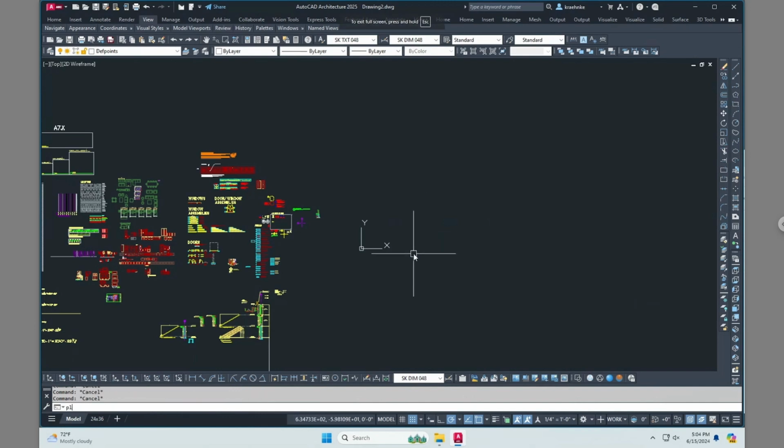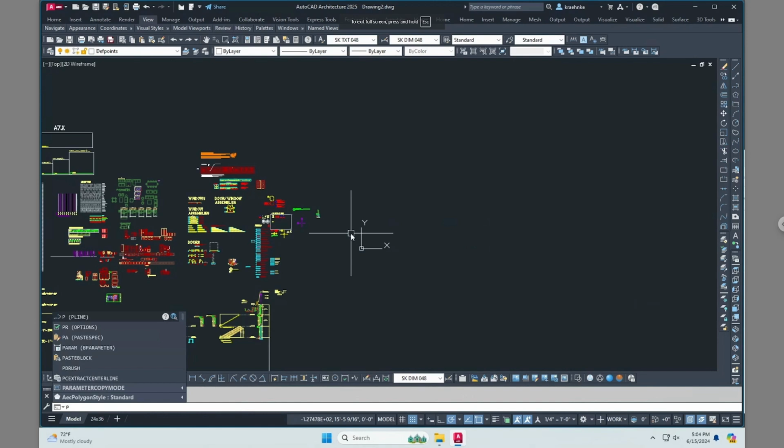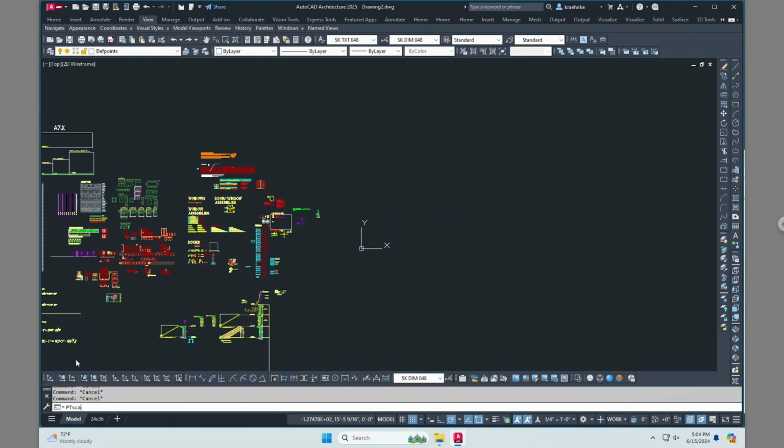What else? Let's check the plot scale. Just make sure that, oh, that's not right. LT, PT scale. Oh, there it is. No. P. Yes. Nope. What is it? P. What is it? PSLT? That's it. Oh, that's paper space. I don't know. I want LTSCALE, my linetype scale.